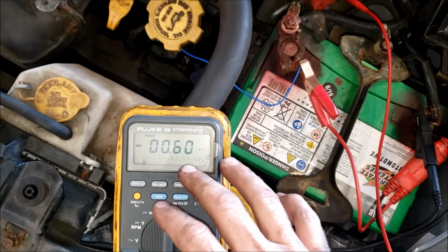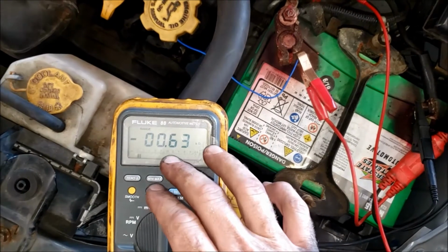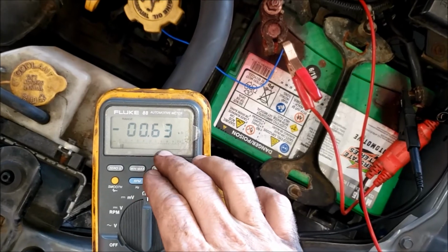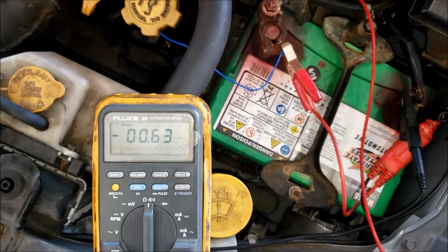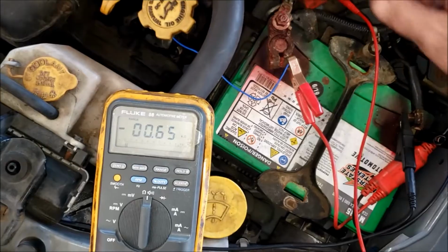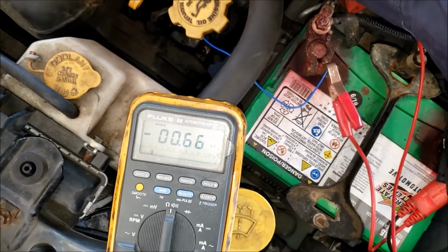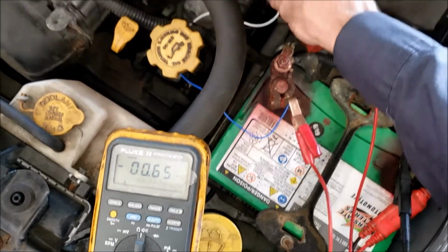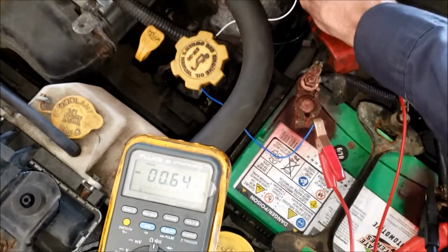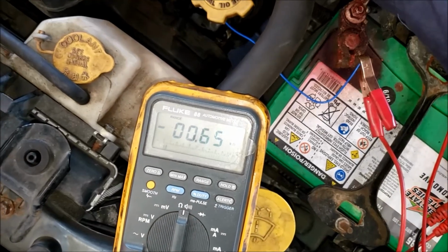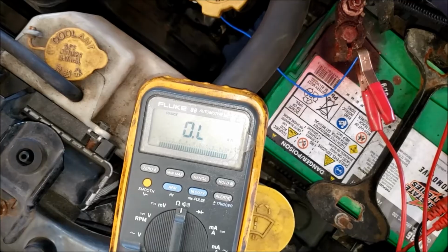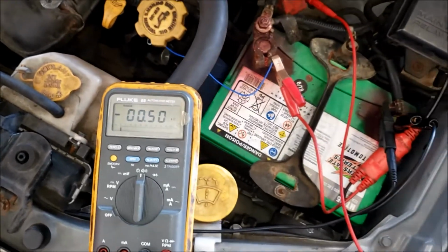All right, while hooking this up, we can now see our problem. We didn't even have to run this engine to see it. We have about 600 ohms of resistance between the oil pressure switch and ground. So that's not good. It should be 0. But if I now take this white wire again and ground out the system, this should go open circuit. It does. So the switch is working, but it has high resistance.